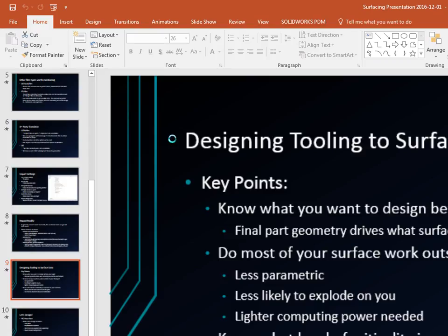So if I had these surfaces here, will it be a variable fillet? If it worked, try it. I've never had, so saving this off as an IGES, bringing it back in so it's just the surface I selected. Okay, now see that. So I want to extend all these right out, right?